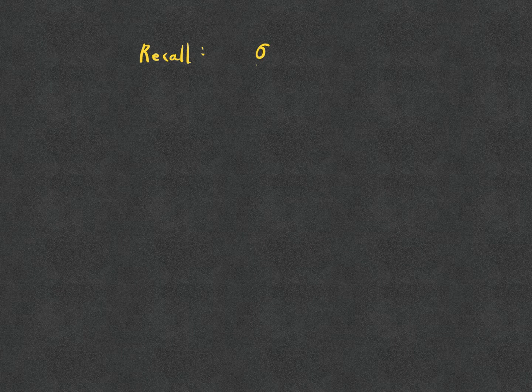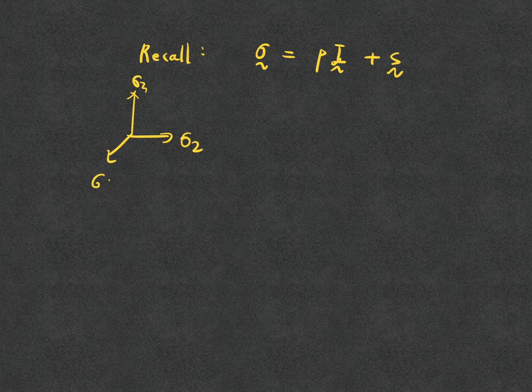We call that sigma is equal to the volumetric part plus the deviatoric part. Now for the stress, I can put it in the principal stress space, and I have a hydrostatic axis p that is increasing, and then I will have the actual shear. Geometrically, I have the total stress, and the stress that is normal to it is the deviatoric stress.